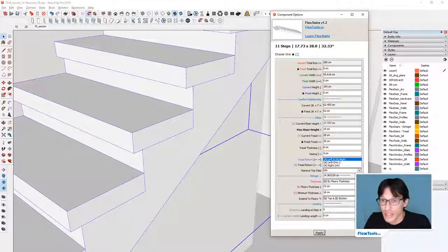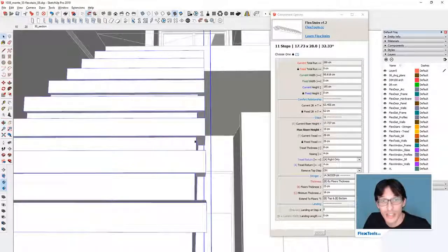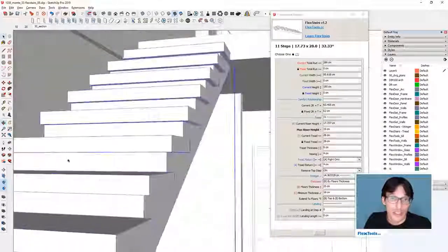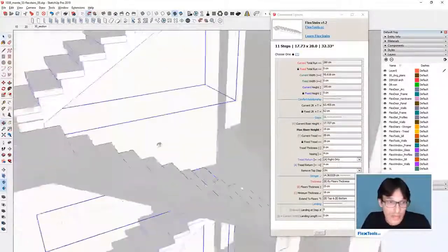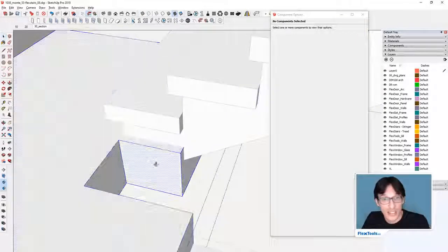And notice there's left and right, or left only, or right only. So if we're looking at the steps, right now we want them to go that way, right? So there we go, you have them coming out. Actually, the stairs stay the same width, but it's the stringer that's getting narrower. And over here you'll see it's right on the wall. So we can do that to all of the stairs. Now of course you have to adjust the landings a little bit.